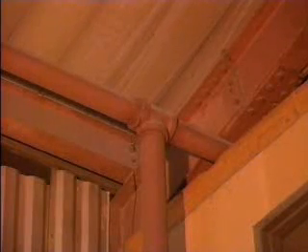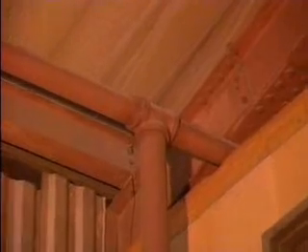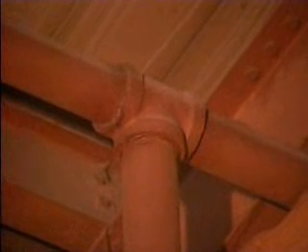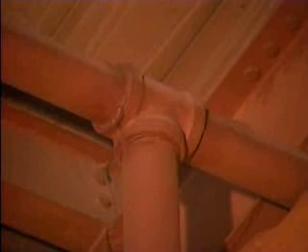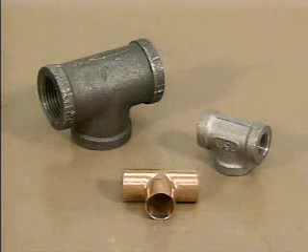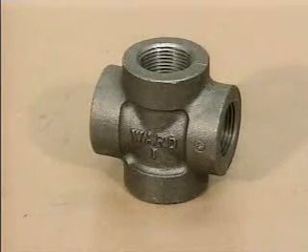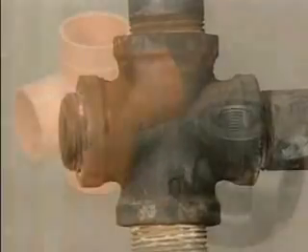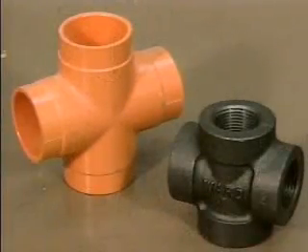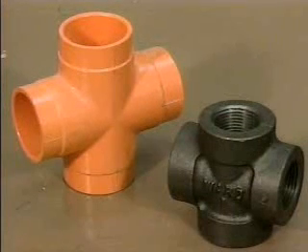Another function of pipe fittings is to provide branch connections. Pipe fittings that provide branch connections are used to divide the flow of fluid in a pipe run into two or more branches. One of the most commonly used branch connection fittings is called a T. T's are used to join a main pipe run to a branch pipe run at a 90-degree angle. T's come in a range of sizes and designs, and they can be threaded or welded to pipes. Crosses are another type of branch connection fitting. The two branch outlets form the shape of a cross. Like T's, crosses can be threaded or welded to pipes, and they come in many sizes and designs.